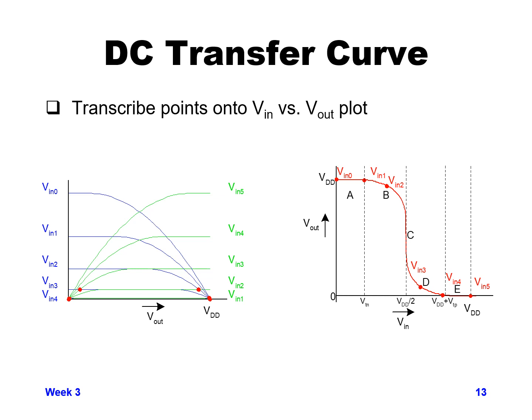It's just the exact point at which the switch happens quickly between VCC and ground will change a little bit depending on the strength of the NMOS versus the strength of the PMOS. But the key thing to remember is we'll pretty much always get a curve that looks similar to that curve on the right. And so let's discuss the nature of that curve and what it means in terms of our behavior.